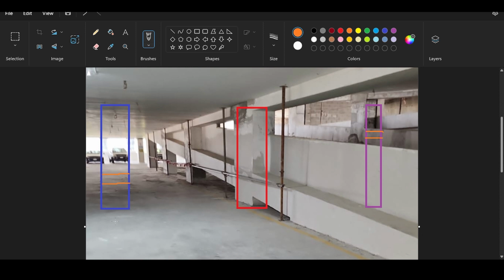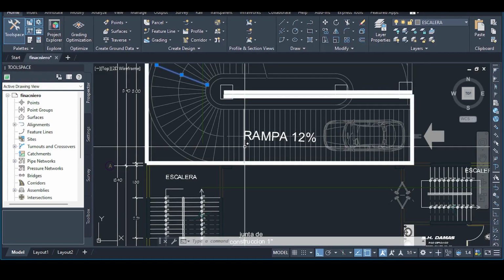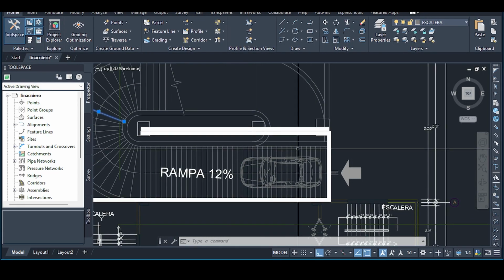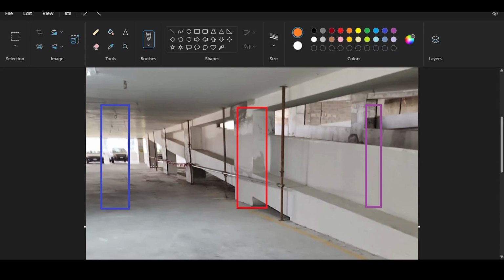Well, because I'm assuming now that the car ramp goes up like this, all the way spiraling up. So a car would go up and spiral around here. This means that the ramp here is low and the ramp here is high. I'm not really sure how the ramp is. Maybe it's vice versa, and I think it's vice versa actually. Oh yeah, see, it goes down from the left side. So in reality, the construction steps would be a high ramp here and a lower ramp here, because the car is actually coming from the top and spiraling, going down, going around the red column and then going down here. So that's my construction steps.